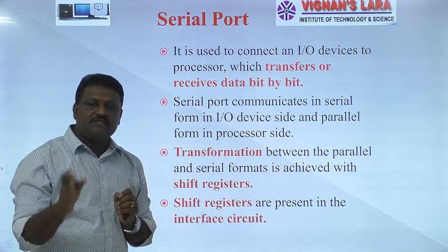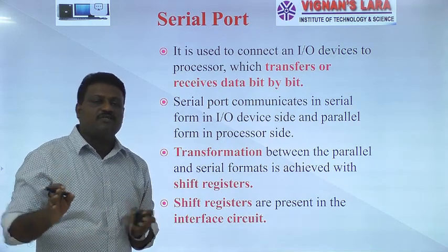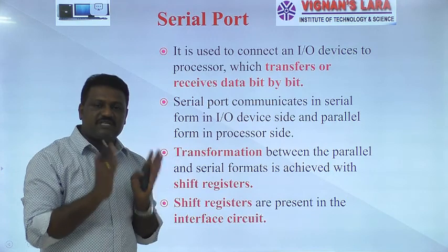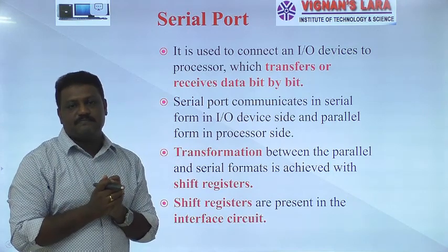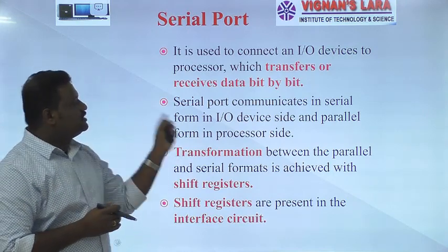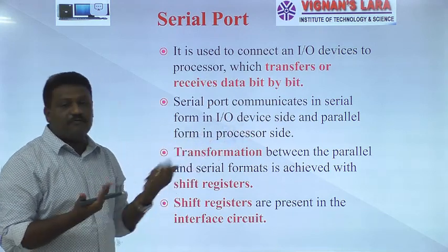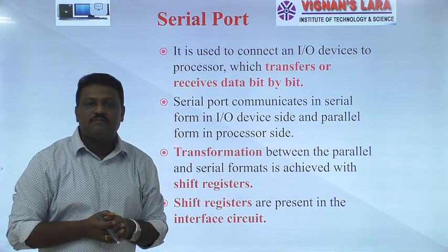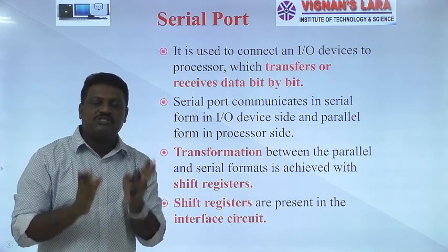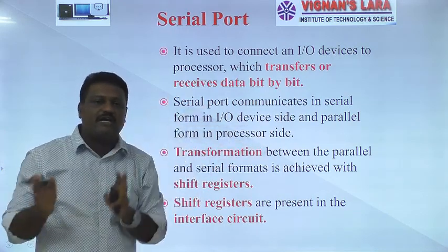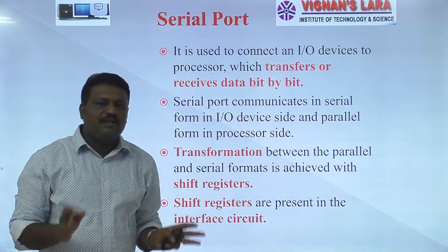So for connecting an external device which knows only serial communication, your I/O interface must have a serial port. The serial port communicates in serial form on the I/O device side and parallel form on the processor side. There is no doubt, because our processor always communicates with either memory or an I/O module, purely in parallel form.